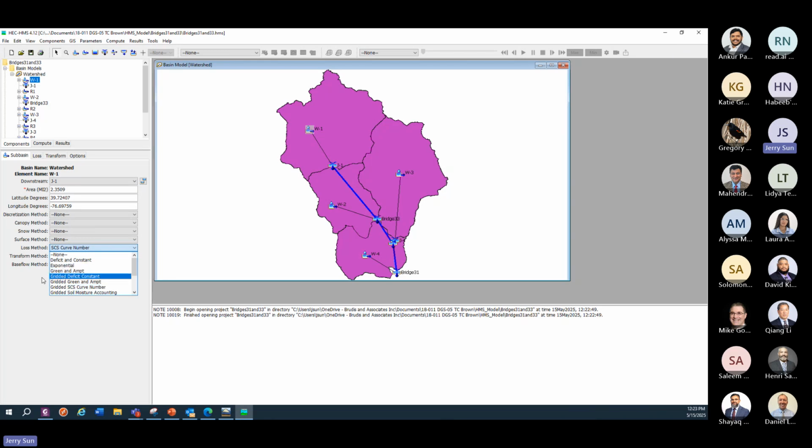The infiltration loss is basically based on the soil being dry, so the saturation rate may be very low, so it loses a lot. That's what this one is. But in Maryland we use, for example, the unit hydrograph. They have different ones, the Clark unit, the modified Clark unit, Snyder, a bunch of different methods with different unit hydrograph curves.